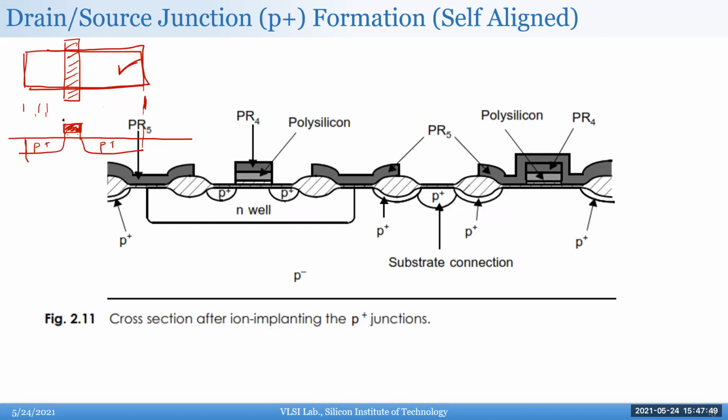So most processes do what's called saliciding. And for saliciding, they will use the poly mask actually. So they will mask out everything else, right? And they'll actually put a layer of salicide and etch it out or ion bombard it, basically, and do the saliciding on this. So they basically use the gate mask to do saliciding. And if it seeps into some of the source drain area, it's fine because it's just conductive.